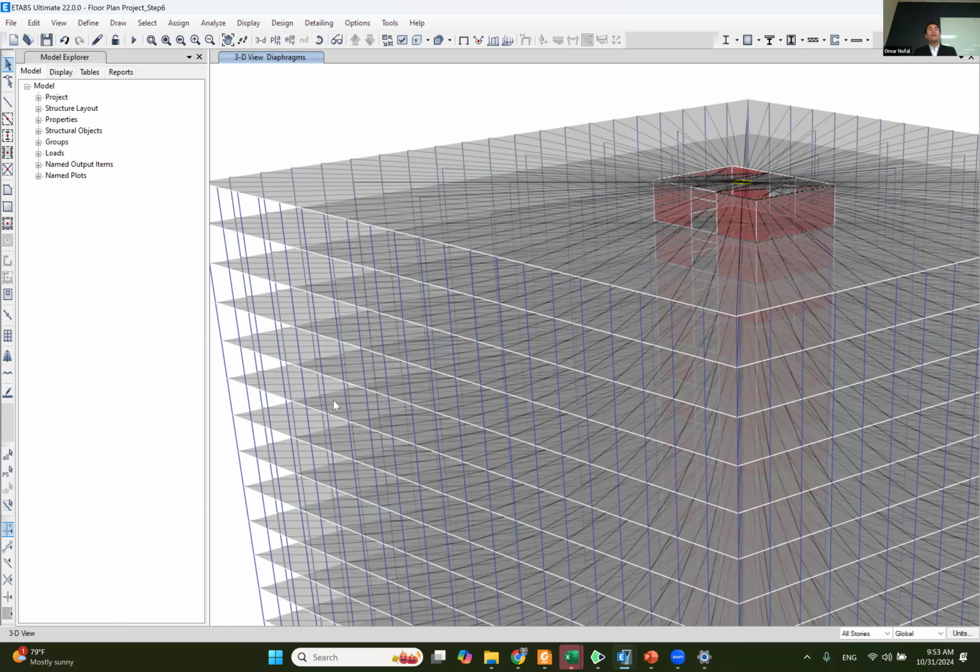And the second thing that I want to do is seismic analysis. For seismic analysis, if you guys remember, we are not gonna use the entire loads of the whole building, because seismic load is a rare event. Maybe it can happen in the lifetime of the structure and may not happen. So it doesn't make sense to design for a rare event for the maximum loading, as if we are assuming that an earthquake is gonna happen at the maximum load.